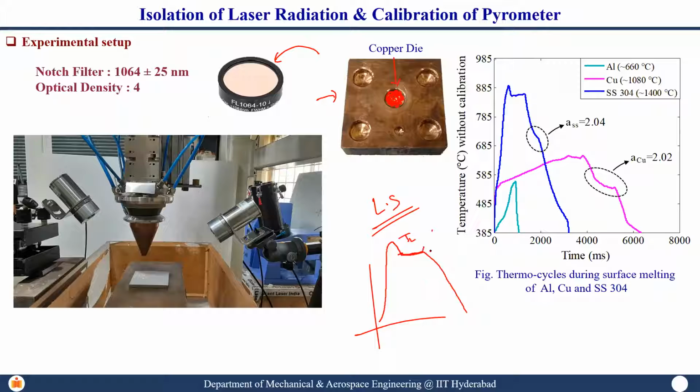So from this you know the solidus temperature and you know the liquidus temperature. And for the selected material you already know both of them, right? So you know these points experimentally, and you know these points prior to that, and then use a calibration factor such that you restore these to true temperatures. This is how you calibrate. This is one way of calibrating.